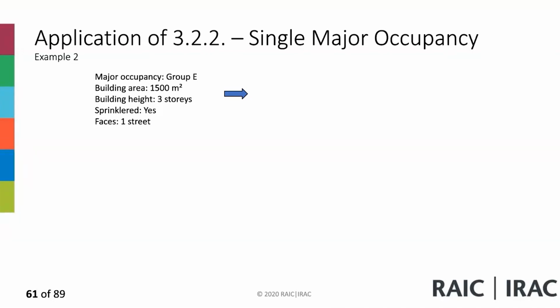3.2.2.65 for group E. So you said 65, so you're going with 3.2.2.65. The building group E is permitted to be, okay, the building is sprinklered throughout, it's not more than 4 stories, and it's got a building area not more than 1,800. So that's good. Okay, so that's one approach.